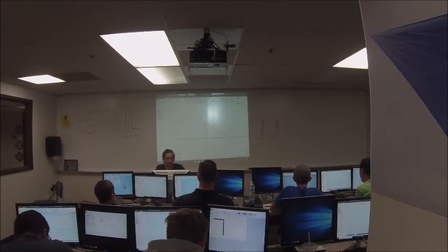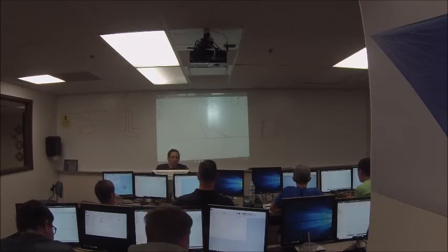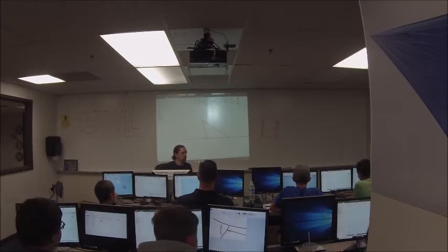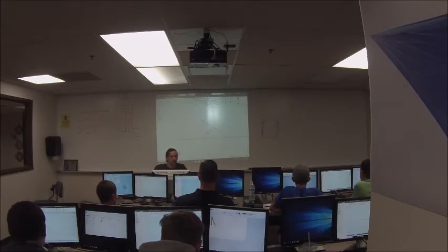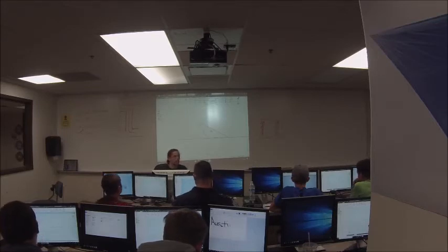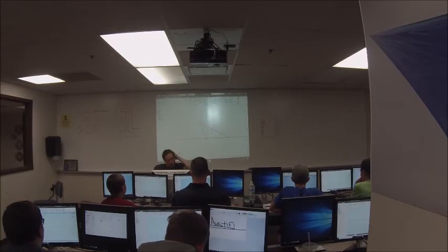Okay. Now I didn't do anything to this other line. This other line can still move around, but now this line is where I want it to be. Now we didn't talk about it last week, but the dimension tool can be used to create angular dimensions as well as linear dimensions. So if I have two lines that are not parallel, and I click the dimension tool, I click one line and I click the other line, it'll create an angle dimension in degrees, so that I can tell it, 120 degrees or something, right? So you can use the dimension tool that way as well.